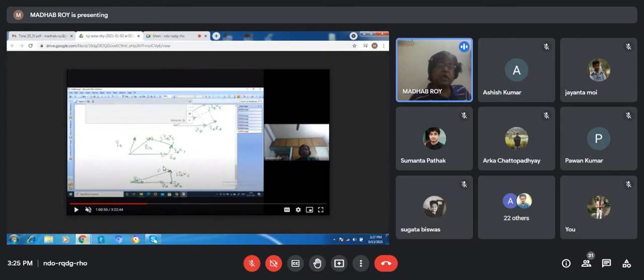Now from the left hand side, you see that if you draw the leading power factor current, then this will be the drawing. That means this will be the terminal voltage and this will be the armature current. If it is a leading power factor, then you can draw this resistance drop into the Phasor diagram, and this is the reactance drop, and thus you can see that here the induced voltage is reduced, less than for unity power factor. So the length is less, that means the field current is less. So when we reduce the field current, it automatically goes to the leading power factor region, and vice versa.